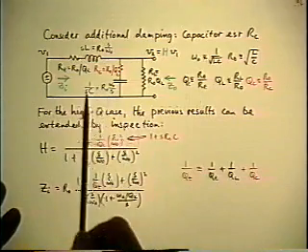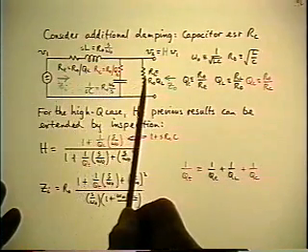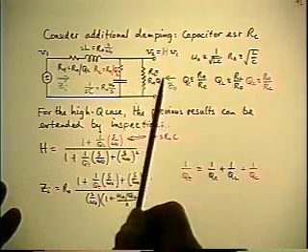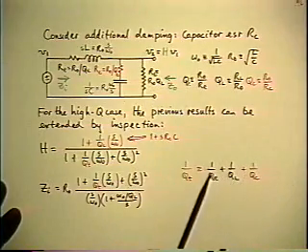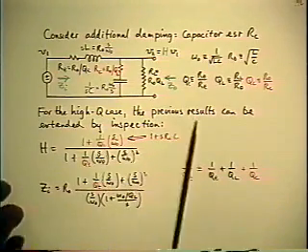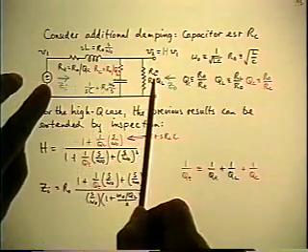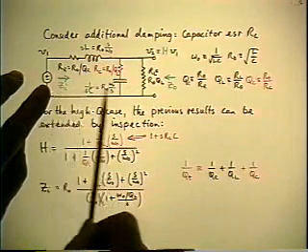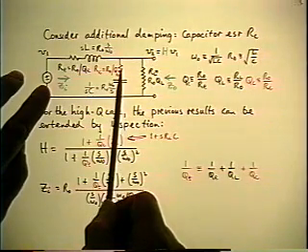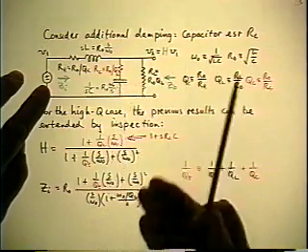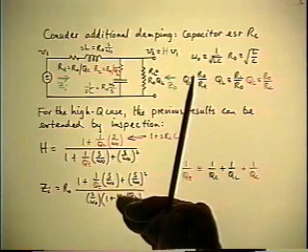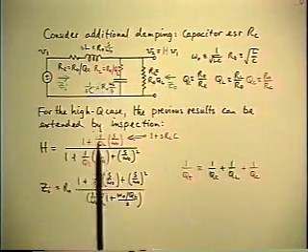So we can use the same qualitative argument of simply looking at the circuit and asking, is there any change of slope of the asymptotes at zero or infinite frequency for the three functions? If there is a change of asymptote, then you know there's a new corner. So in this case, we're looking at the voltage transfer function. Take zero frequency. The cap is open. Does it make any difference whether the RC is there or not? No. It's in series with an infinite impedance. Makes no difference. Therefore, there is no additional inverted pole or inverted zero resulting from that resistance.